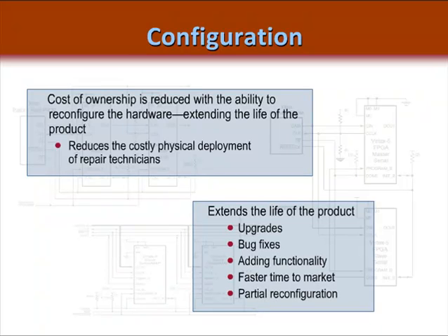This has given way to the concept of partial reconfiguration. Partial reconfiguration allows part of an FPGA to be reprogrammed actively while the device is operating. To illustrate, take a laser printer. You could build a controller as part of the FPGA design and have a series of buffers that are reprogrammed actively, based on the font or paper size the user selected.